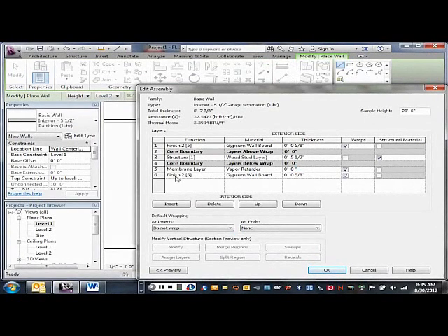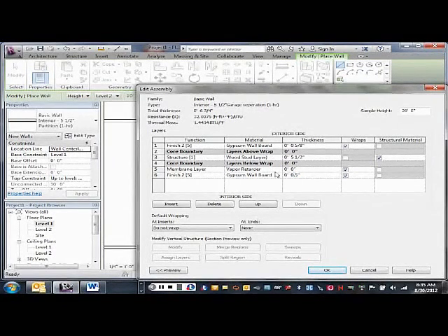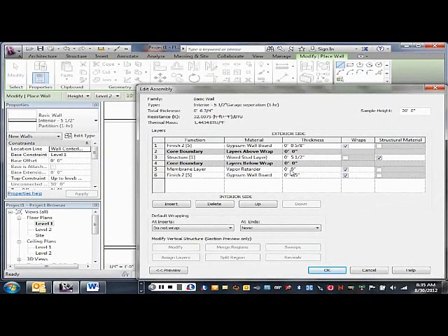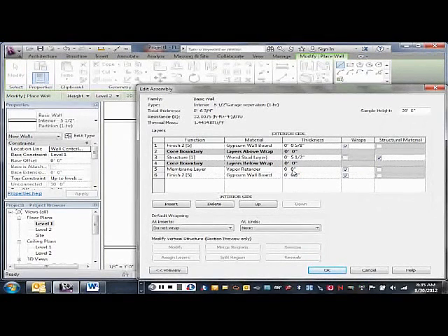And then I will have my layer of, on the inside, I can get by with 1/2 inch sheetrock in residential. Okay, so now I have 5/8 gypsum board on the garage side. I have the 2x6 stud. I have the vapor barrier on the inside, and then the sheetrock.